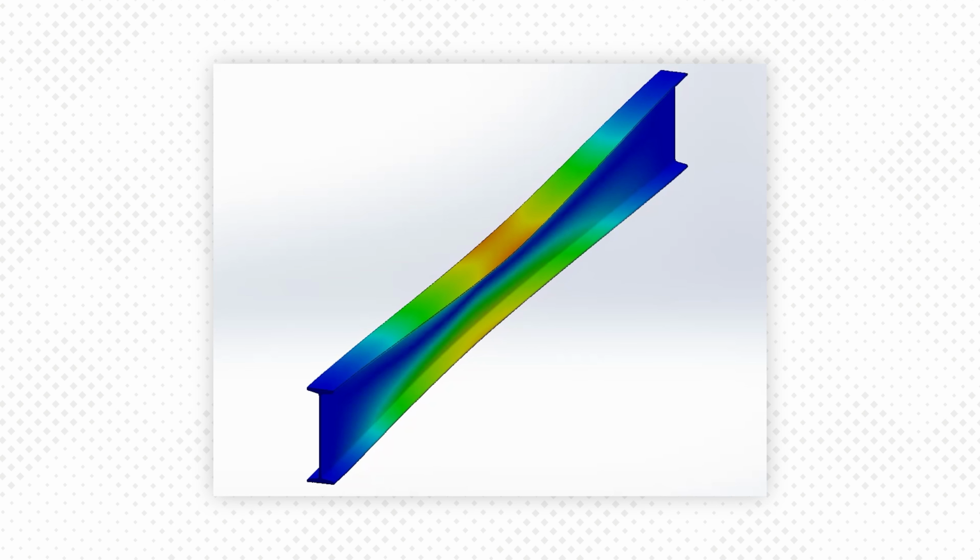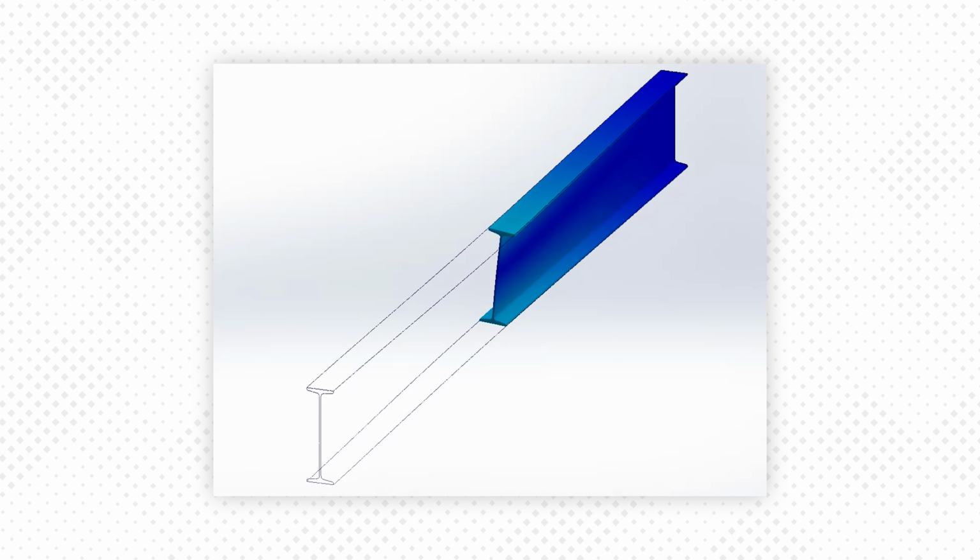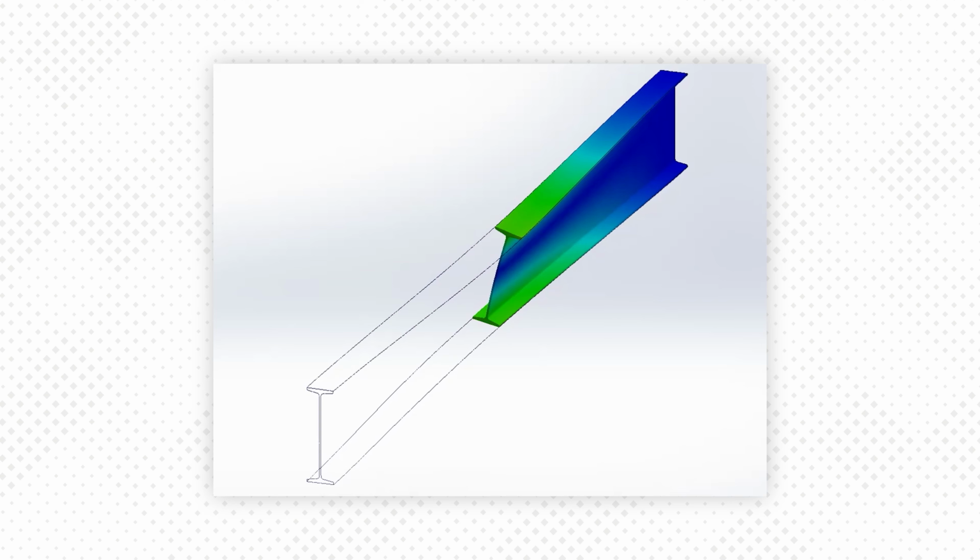So lateral torsional buckling happens with I-beams. An I-beam is really good if it's loaded as it was designed to be loaded. So like on a steel girder, it's designed to carry the load in the vertical axis. And as long as it's vertical, it's going to operate just like it was designed. But if you take an I-beam and it's just by itself, it's going to get squirrely. Even picking up an I-beam, it's got specific pick points. If you pick it up at the ends, chances are it's just going to bend right in the middle.